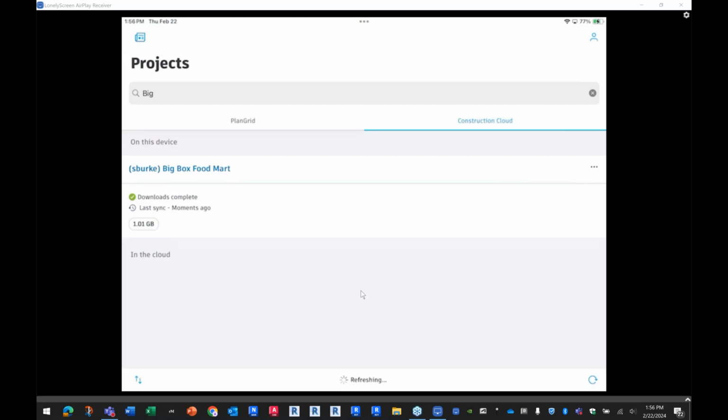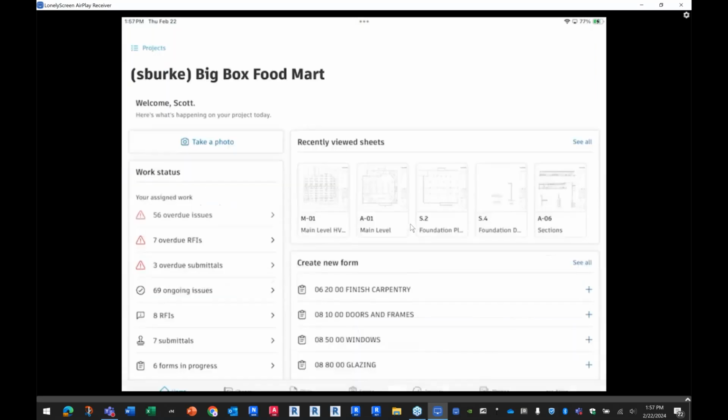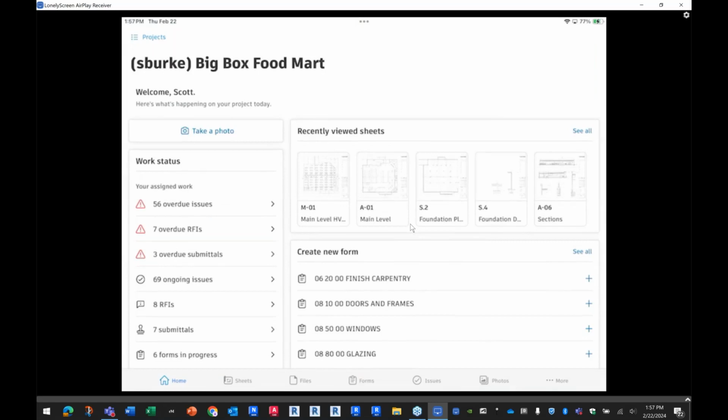But this first question: is there any format of a coordination model that is usable at all in the module of the ACC? Is there any that actually works in the ACC app? And I responded, essentially, yes, you can view NWCs and NWDs in both desktop and mobile. You can do various activities with them. You're not seeing them in their quote unquote coordination context with the actual clashes. Right, you won't be able to see the issues that have clashes in them in the model itself. Yes, indeed. So you can fully view the models though.